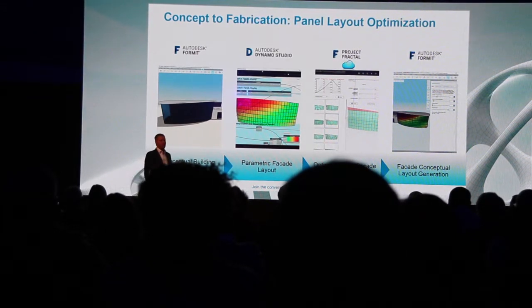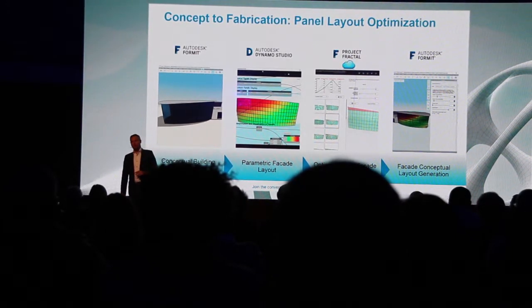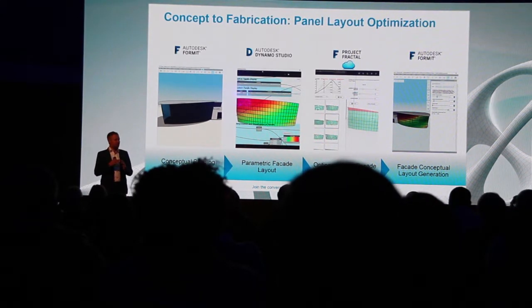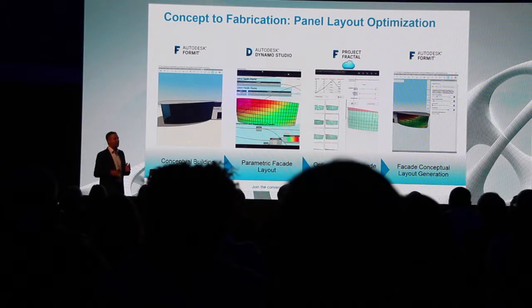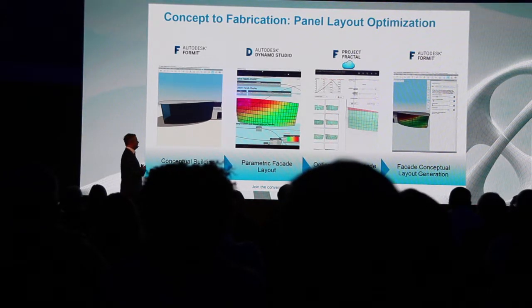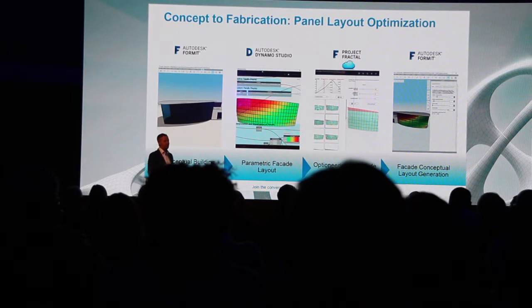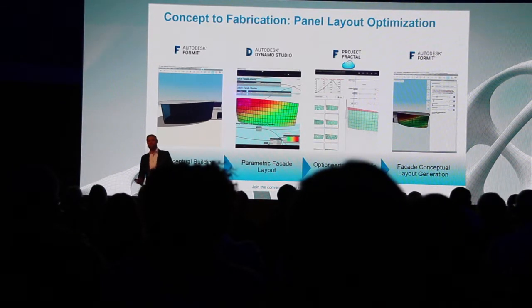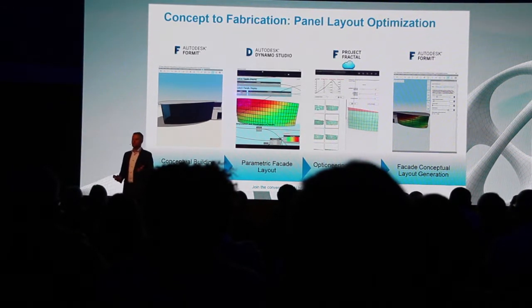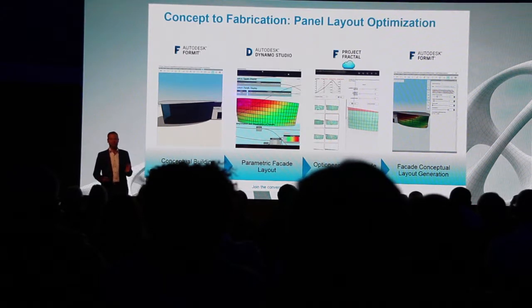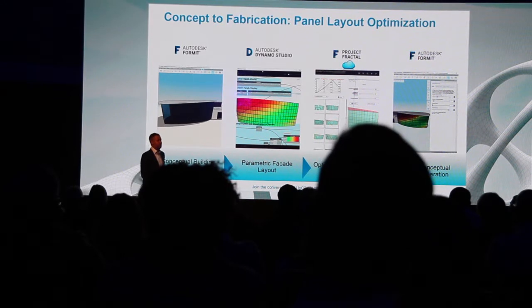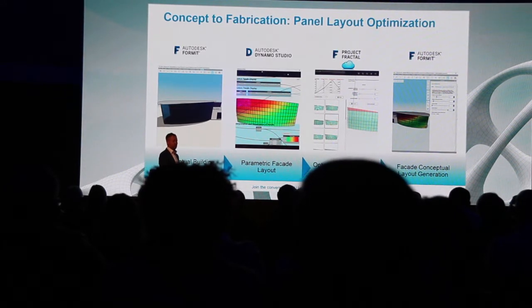Another problem that you can have with paneling is the angles between two lines, so you have 4 corners in a rectangular panel. Now, in an ideal situation, every corner is 90 degrees, but we are not in an ideal situation. So this means that every corner will possibly have a different angle, something between 85 and 90 degrees, which might give you a problem again for the fabrication of these panels.